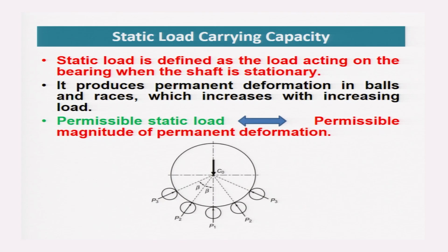Now, the permissible static load, that means the maximum static load that can be applied, will depend on the permissible magnitude of the permanent deformation. That means what amount of permanent deformation can be allowed under static load condition will govern the maximum load carrying capacity.